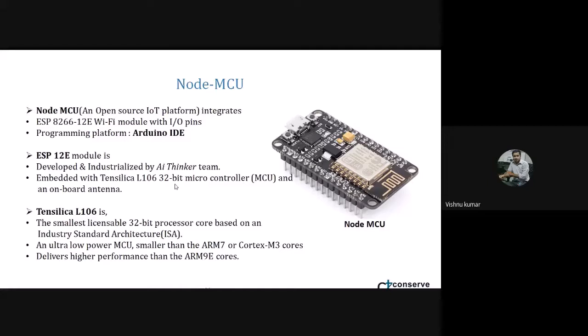We can go through the Node MCU. Node MCU is the basic working platform, an open source IoT platform for Wi-Fi, and inside it an ESP12 is embedded and placed in the Node MCU. Multiple IO pins and analog pins are there.